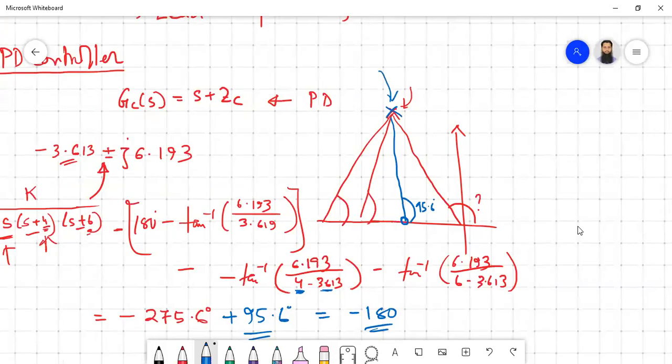Now again the question comes whether you have to plot the root locus again. The answer is that this time you actually have to do it, because we are introducing one zero, and because of that the direction of your root locus will change. So this one will be going from this one to this one, and these two will be merging together, and then they will somehow follow a path like this, and eventually it will go through that point.